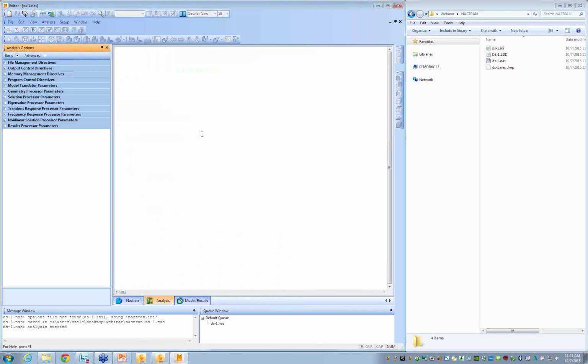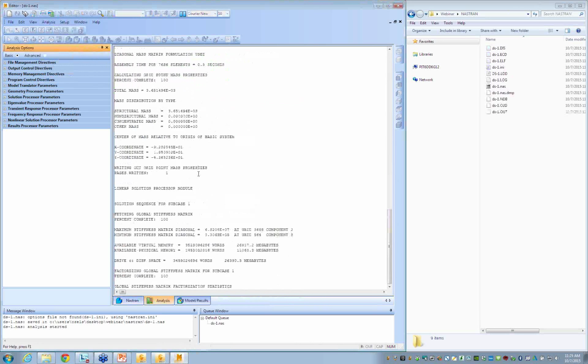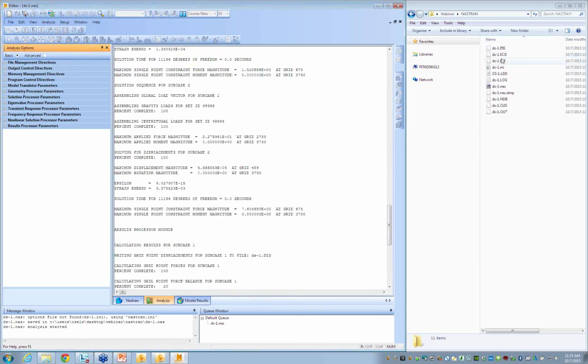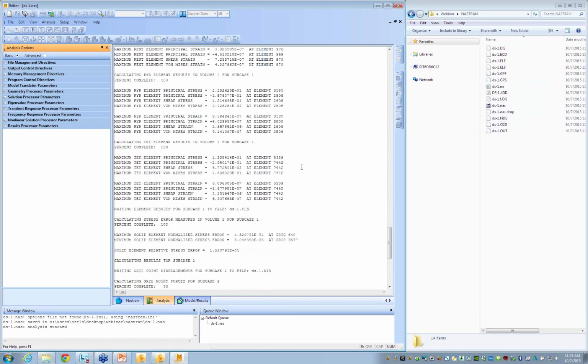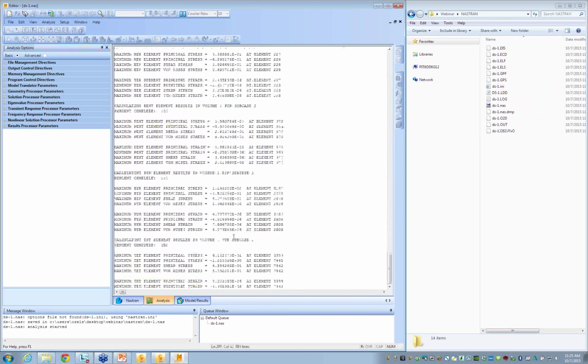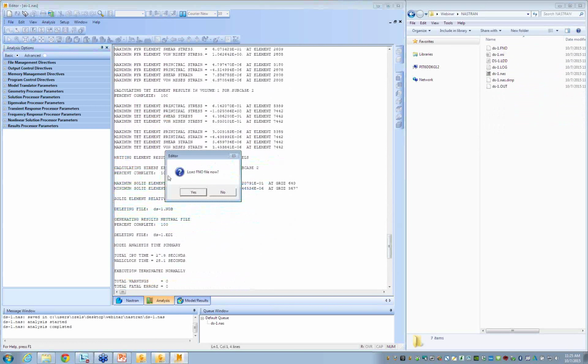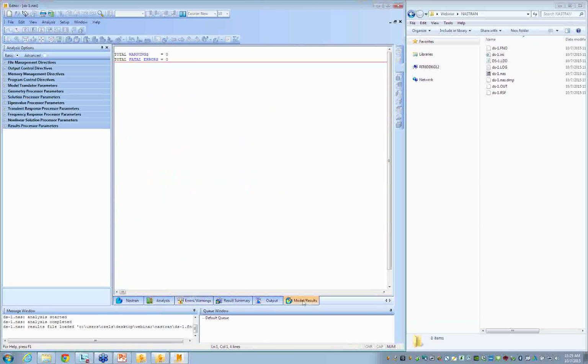All right, so I just hit run, and it's running. It takes a little bit of time, and as you can see, Nastran solvers populate multiple files as well. And it's calculating all the stresses and deformations just like the SimMech solvers are doing. And now it finished results for subcase 1. It moved on to subcase 2. And it finished. So let's say I want to load the FNO file and go into the results.